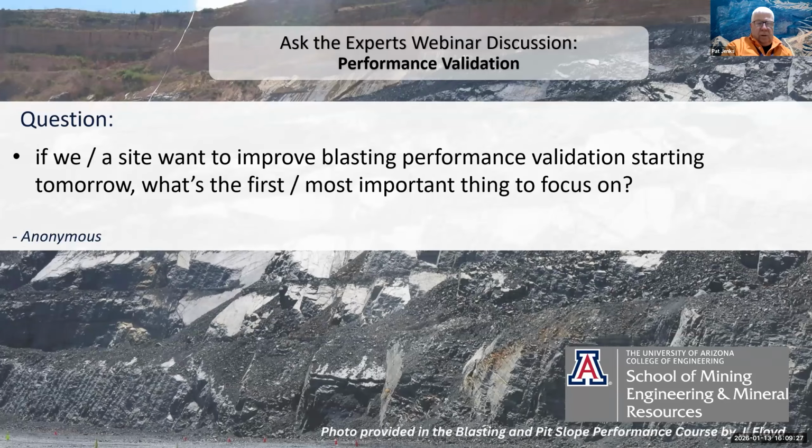Yeah, I would say one of the things that I would like to see operations focus on, because I see this as a big issue at many of the sites that I visit, is that we're not achieving our catch bench width, and that is a safety element to protect our workforce from rock fall and spill rock.